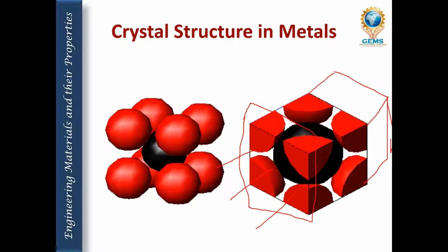The elements which crystallize in BCC structure show the property of metallic conductors. They have an 8-fold coordination in the nearest neighbor shell. That is 8-fold, because these atoms will be shared by the other cubic cells, right? So this is an 8-fold coordination, which does not permit saturated bonds.